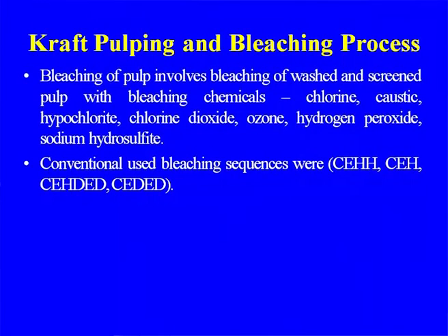These are some of the developments in pulping. Already we have discussed the bleaching of pulps. The conventional method of bleaching was CHD, then they added chlorine dioxide. Now we are talking about oxygen also, as pre-bleaching or pre-delignification, that has also been added, so OD, not C, because C is chlorine, then oxygen, chlorine dioxide, and then extraction. Extraction is an integral part with the caustic, and all the lignin compounds are removed during the extraction stage, which is why the extraction stage is highly colored.